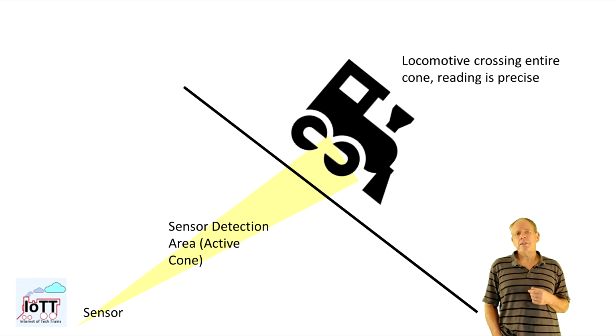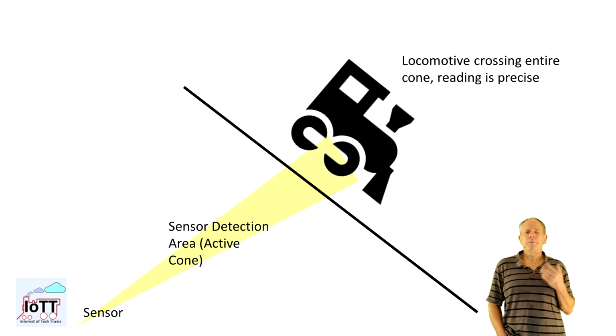One approach would be filtering the read values, but this would slow down the detection process as the result would have to be based on more than one readout. The other option is checking the flux value of the readout and only consider the distance measurement if a certain quality of the readout is detected. However, before I can do that, I need to better understand the meaning of the flux value, which seems to fluctuate quite a lot, so more research is needed.